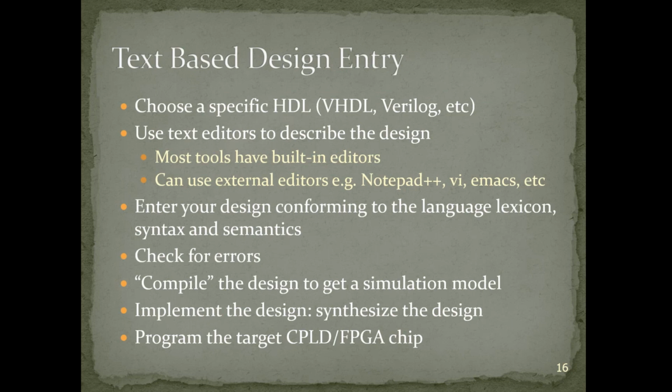The primary form of entry, though, is really the text-based form of entry, where essentially we can choose a specific language like VHDL or Verilog, and other tools might support other languages as well. So when you create a new project, you select what your language is going to be, and the Xilinx ISE allows basically to select both VHDL or Verilog, one of the two. Of course, in our case, we'll be using VHDL. And then basically you just use the type editor with syntax highlighting to type the design in.